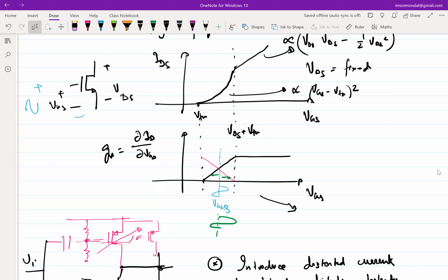Even if it's a small signal, what is small or large? We are basically choosing to neglect the others, right? So all of them are always there. Given that they are there, we would like to characterize how much distortion we have. Again, these are weak distortion, which means that the fundamental is always much stronger than the others, right? Now, in analog circuits 101, we choose to neglect them. What I'm now saying is that when you make a real product, you cannot neglect them. Bring them into the picture and see what effect it has. Even small amounts matter, even if it's 100x lower, it will still matter.